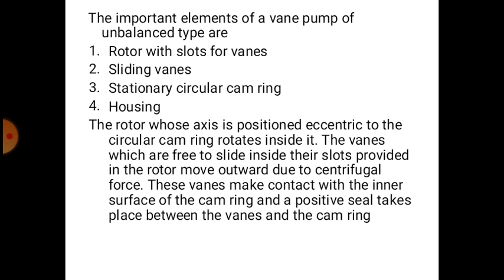The rotor axis is positioned eccentric to the circular cam. So circular cam and rotor, they are eccentric. The rotor axis is positioned eccentric to the circular cam ring, and rotates inside it. The vanes which are free to slide inside the slots provided in the rotor move outwards due to centrifugal force.